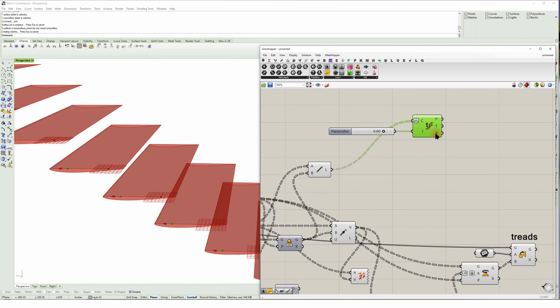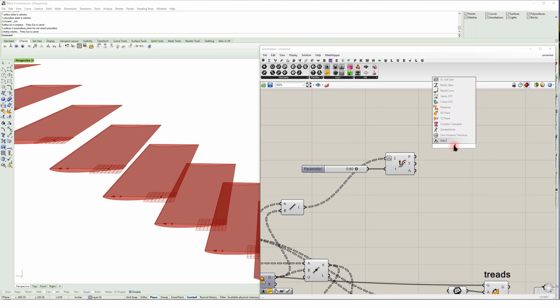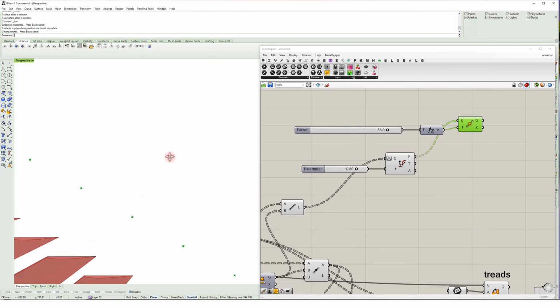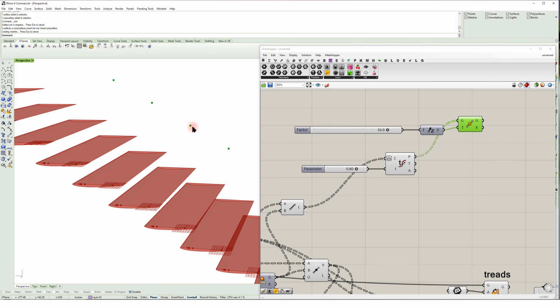And now I'm going to move, let's go move in the Z direction. So type Z. And by how much? Let's give ourselves another slider. Let's actually go negative, -6 less than 36 less than 42. So that's going to give me a slider starting at 36. And plugging in my point to that, you can see that's going to move these points vertically.